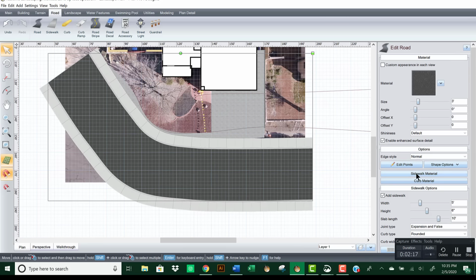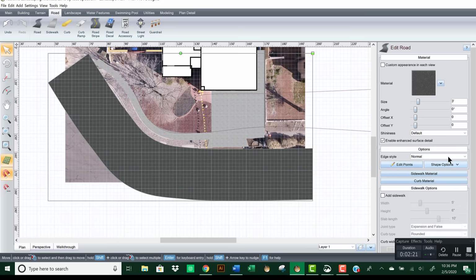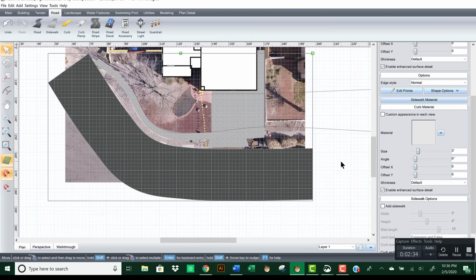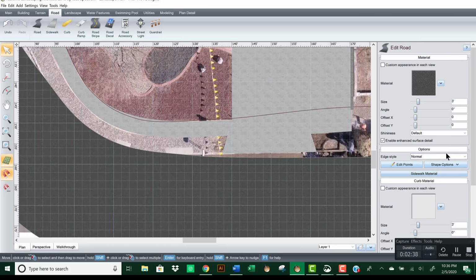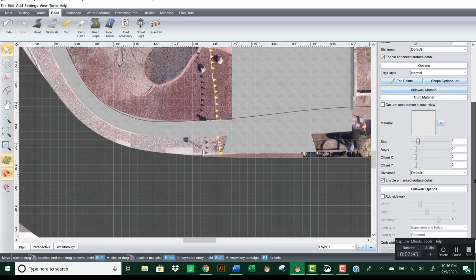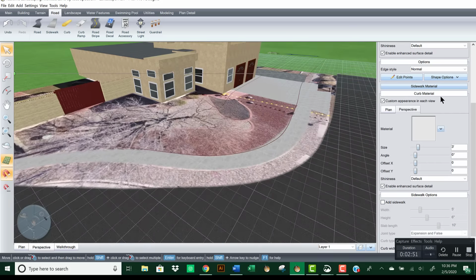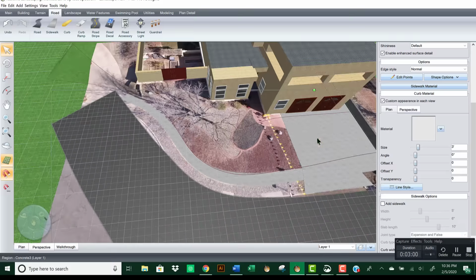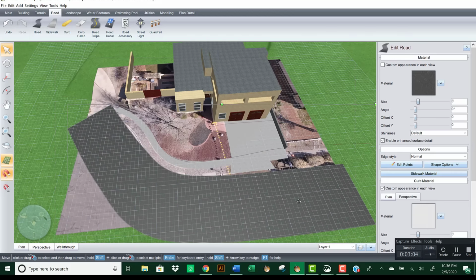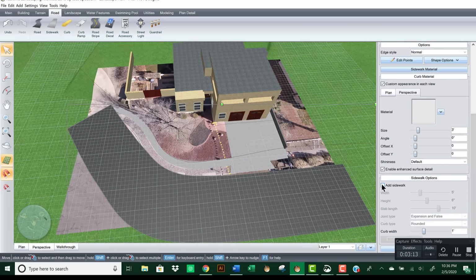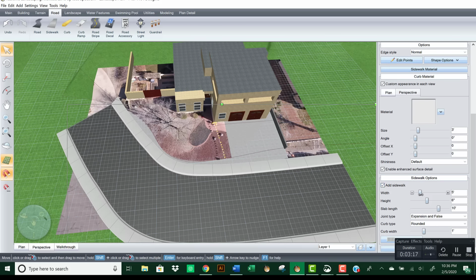You can see it comes with a sidewalk. We are going to remove the sidewalk, but we're going to click on curb material and say custom. Oh no, hang on. Tricky. There's a bunch of little details that, I'll be honest, we don't always remember. Curb. Trying to think of how to add a curb. We'll add a curb separately. Okay. For the street, I'm going to tone down, hang on, let me fiddle around with this a little bit.